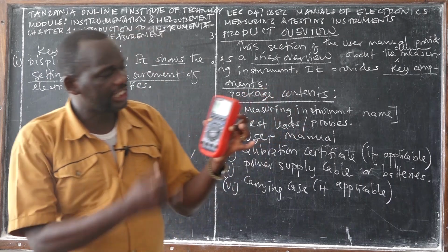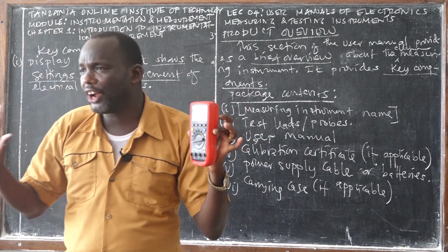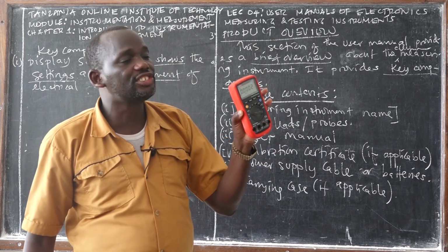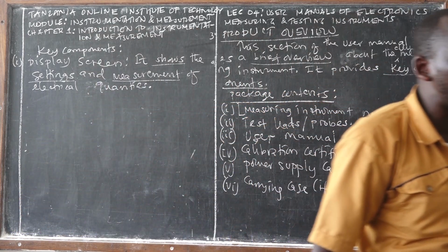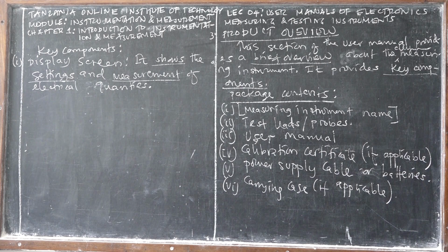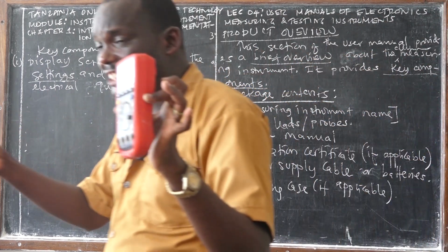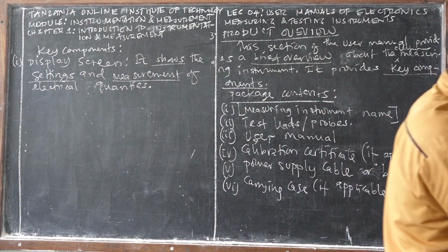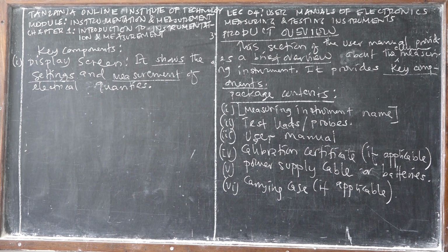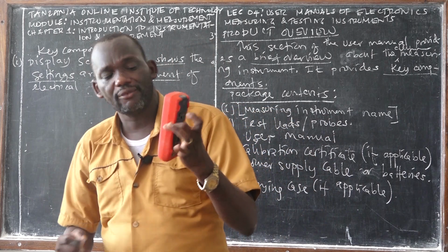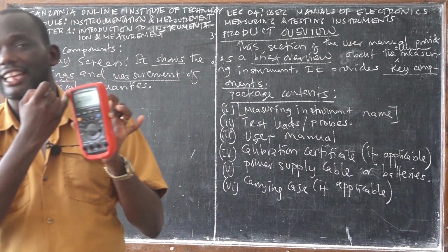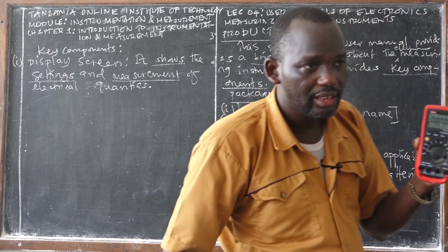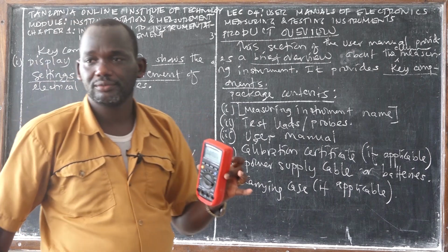Okay, look here. In this digital display right now, there is no setting and there are no measurements displayed. If I turn it on to AC or DC voltmeter, right now you can see some numbers. So within this display there are settings and the electrical parameter. For instance, once I rotate it once, it shows DC volt, which means this is a DC voltmeter. You set the digital multimeter to operate as a DC voltmeter, right? But it also displays 0.0000 volt.